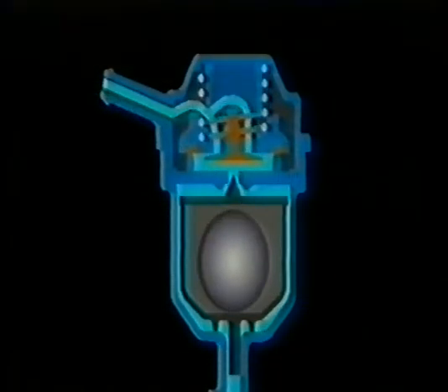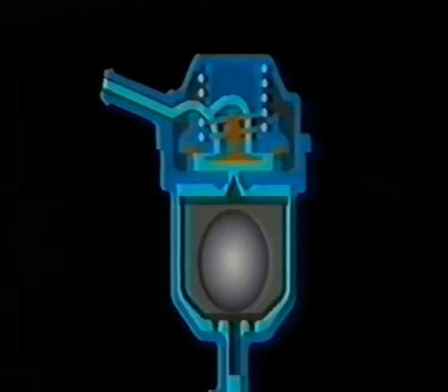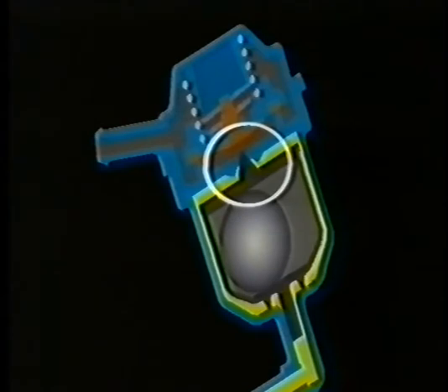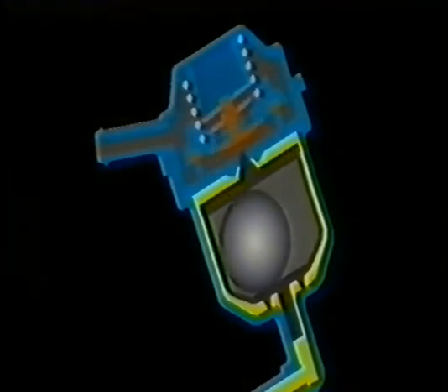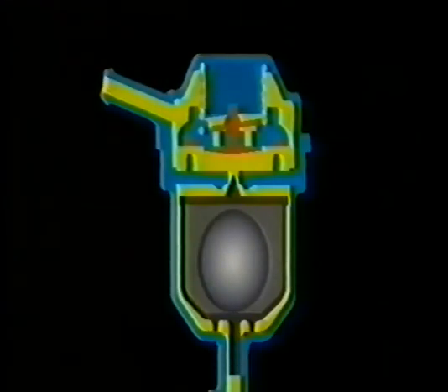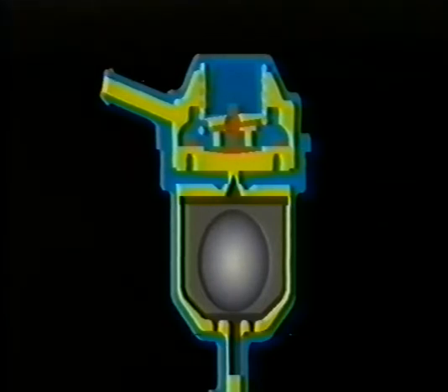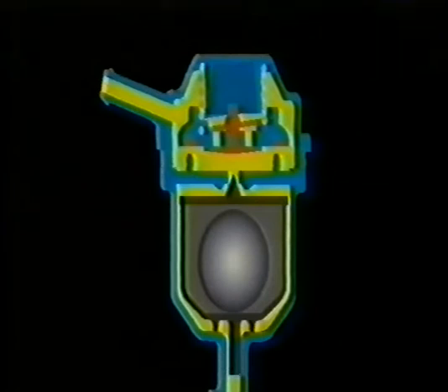The lower half of the ventilation valve may include a gravity valve, which prevents fuel from spilling out of the breather pipe in the event of the vehicle turning over during an accident. This is done by a ball which moves this cone valve onto its seat, so closing the outlet. Because of this gravity valve, it is important that the ventilation valve is always fitted vertically on the vehicle. There are various types of ventilation valves, so always consult the parts microfiche when renewing one.